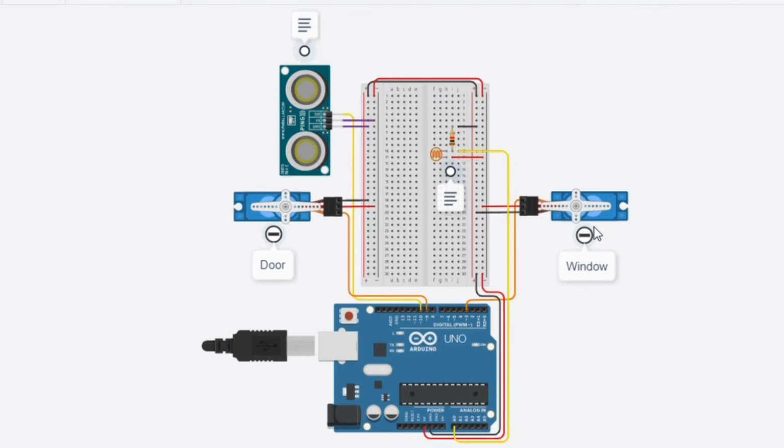So next we move to the wires' function. The black wire from ground is connected to this breadboard, so the whole line here is considered as ground. While the red wire at 5 volt at this Arduino Uno R3 is connected to this breadboard, and the same goes for the ground. All these lines here are now at 5 volt. So every component here is connected to the 5 volt and ground to complete the loop.